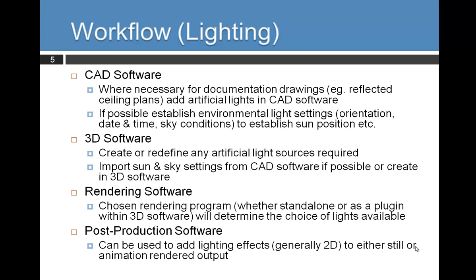The rendering software as well needs to be thought about because it's going to determine the lighting options. I'm going to be focusing on mental ray, so all of those lighting tools we'll be able to use, from the photometric lights to the MR lights, which are really good, as well as the old standard 3D Studio Max lights. But say if I was using V-Ray, it'd be a different set of lights. Again, Maxwell uses materials for lights. You don't even have lights in Maxwell. You have different kinds of materials, and some materials are bright and some are not.